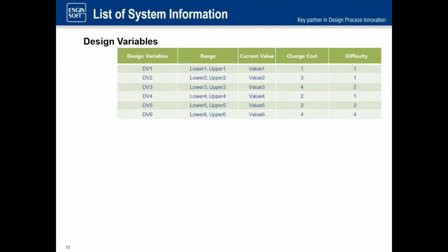So it's very important that these ranges be set as best you can, because if you set them too wide, then the design of experiments is going to cover a huge area, and maybe you're going to lose some resolution. Of course, you can always gain it back by doing more runs in the DOE, but that takes more time.